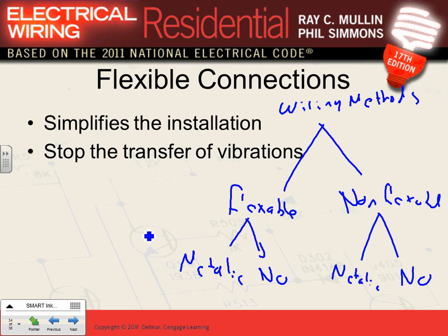So first, are you going flexible or non-flexible? 99% of the time, we go non-flexible when we do conduits. When do we use the flexible, guys? Typically in dwelling, well, in anything, to tie to equipment. It absorbs vibration and makes it easier for us to move the equipment. When you do commercial, I dare say probably 90% of your wiring method is non-flexible.